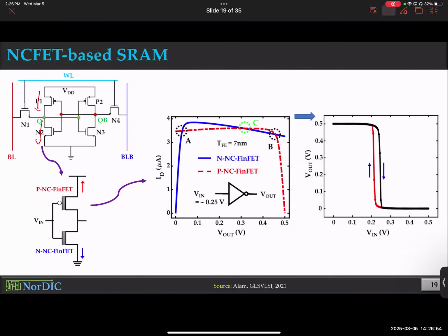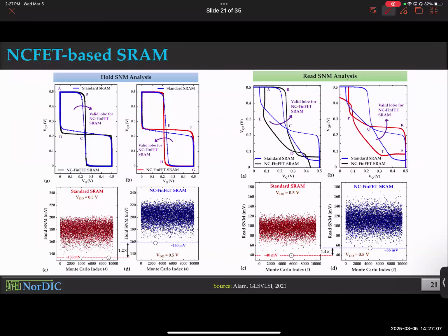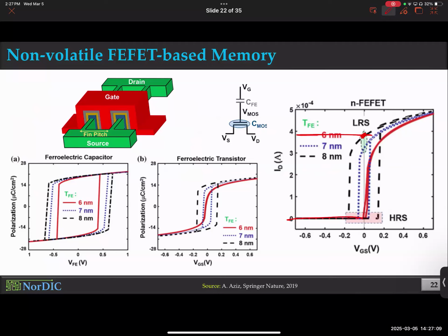But if I could completely get rid of VDD, if my SRAM could still remember what was stored, then there is no problem. I don't care if it is a leaky transistor. Okay, so now getting back to this point, will ferroelectric remember how it was programmed even when I remove the voltage?